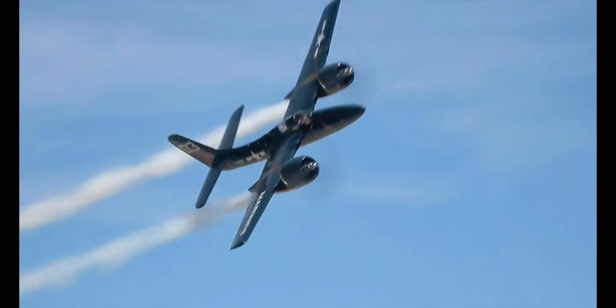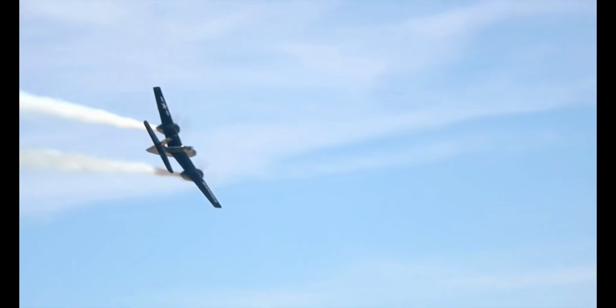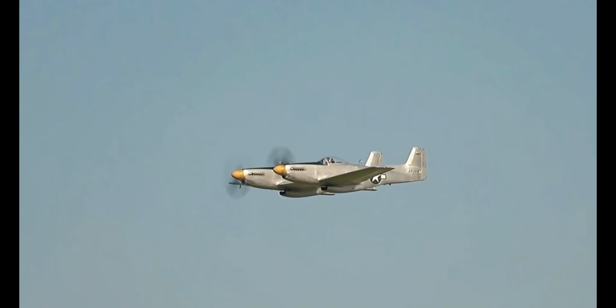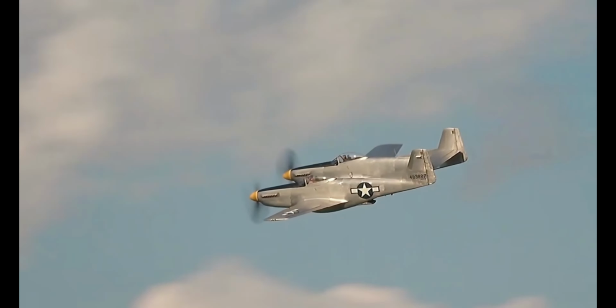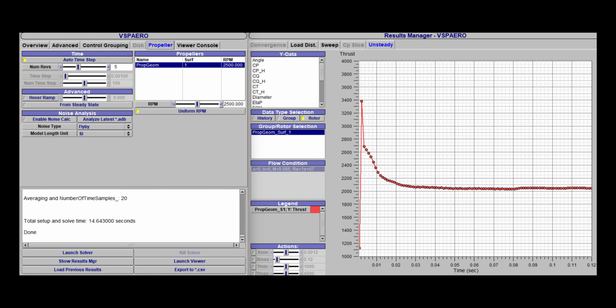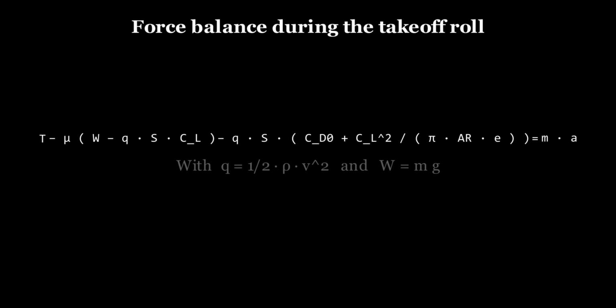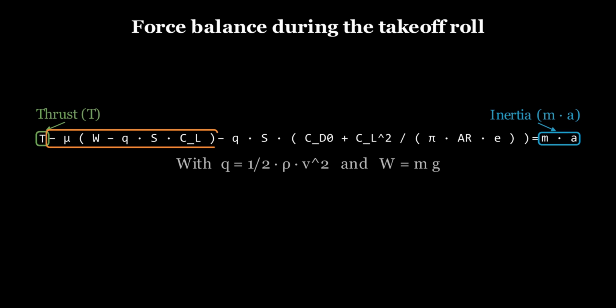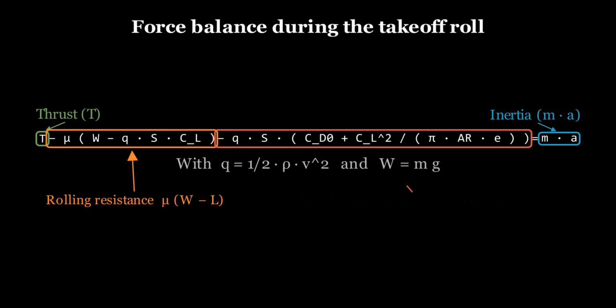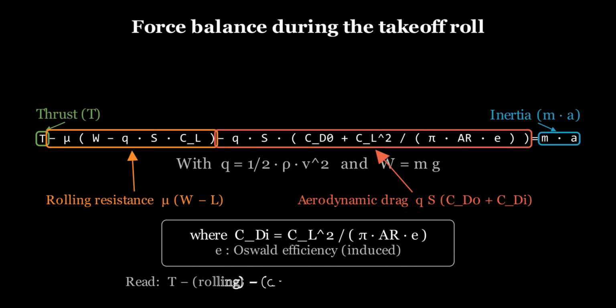However, in my opinion, if more refined thrust calculations are needed, tools like ANSYS Fluent or Star CCM Plus should be used for simulation. With the adjusted propeller parameters, the calculation shows that the stable thrust at maximum rotational speed is around 2,050 newtons. The takeoff thrust must overcome three main components: the friction drag of the airflow, the parasitic drag, and the induced drag. With OpenVSP, it is also possible to calculate the average CL and CD0 of the full aircraft model.